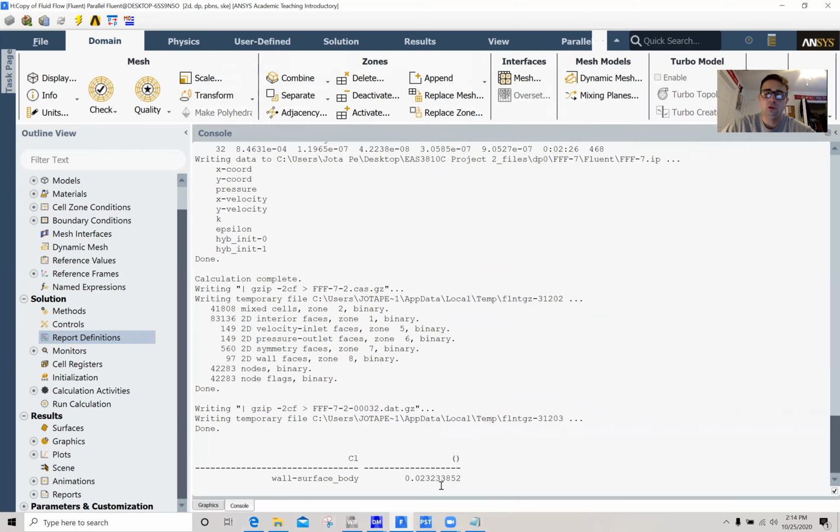And your lift coefficient at 0 angle of attack is actually going to be a little bit greater than that of the symmetric airfoil, NACA 0012, because, again, you have that camber, which is going to cause a slight pressure difference, which is going to give you a little bit of lift.